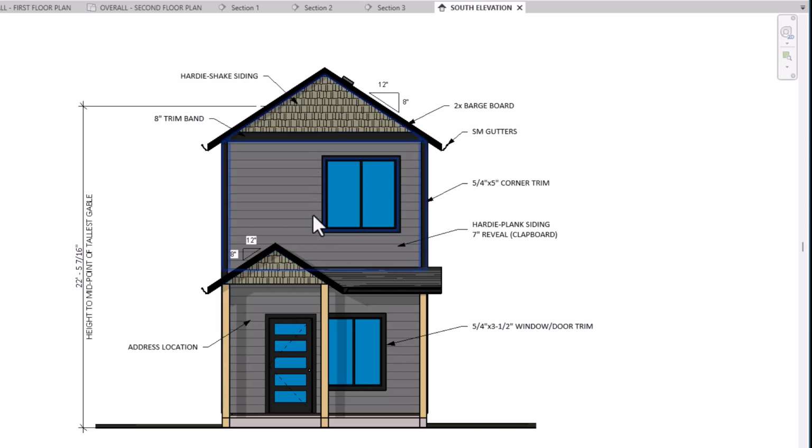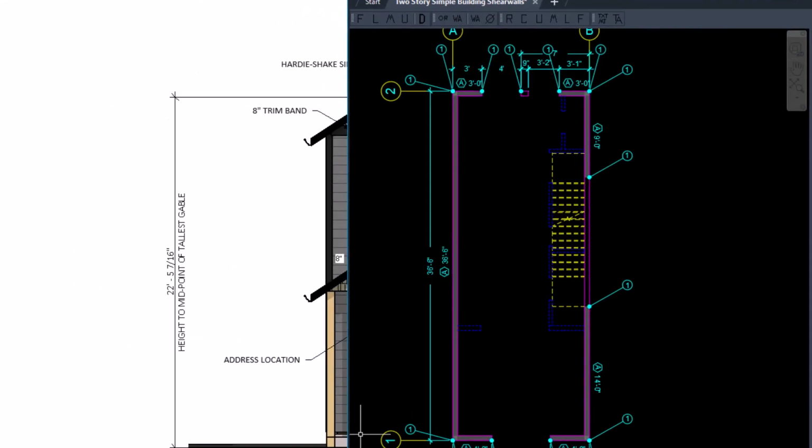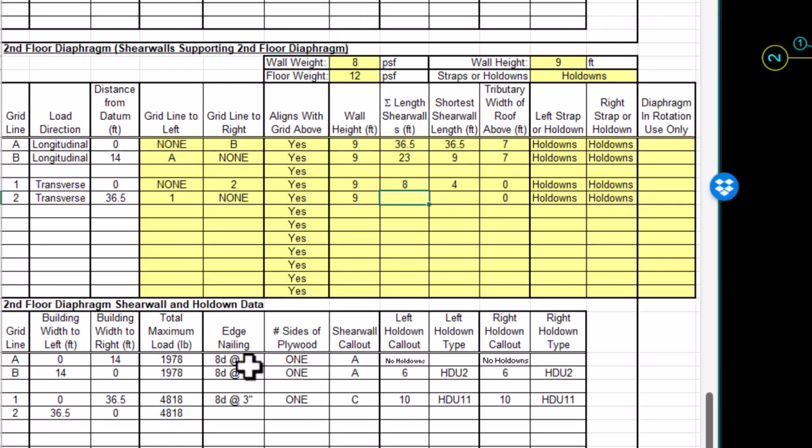And there's also another strap right here that's next to the edge of the window upstairs, and it goes down and lines up with the framing that's in between the front door and the window right here. So let's take a look and see what all of that means. Oh, and then downstairs we have a 3-foot shear wall on either side of the door and window package.